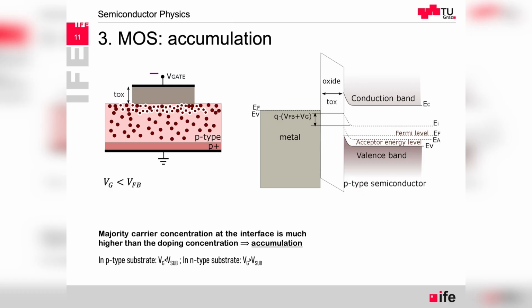The band diagrams are bending upwards in the P-type semiconductor, where we talk about the hole concentrations. You can see that the Fermi level, which is constant, is further away from the intrinsic level, which is bending close to the interface, and closer to the valence band. So it's as if there was a higher doping, a similar effect we can say, but in fact this is not controlled via doping, but via applying the potential. So this condition is called accumulation.